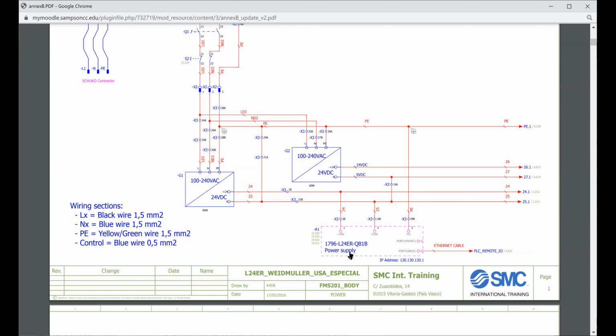So it's completely DC. Now, these PLCs over here that we used in the summer program, you put 120 volt in, and they've got 120 volt inputs. All the push buttons and everything is AC going in, 120 AC. The solenoid, the fan, and the lights, everything on there is 120 AC. There's no DC in that system. So some PLCs are completely AC, some are completely DC.